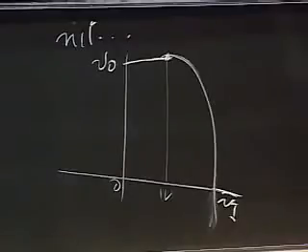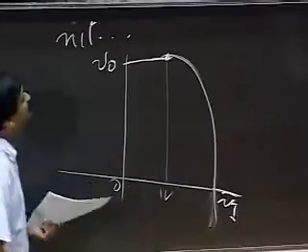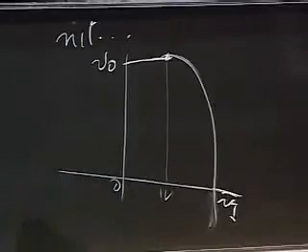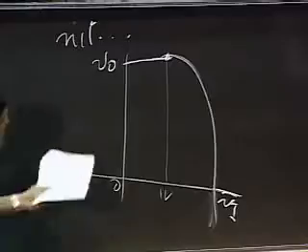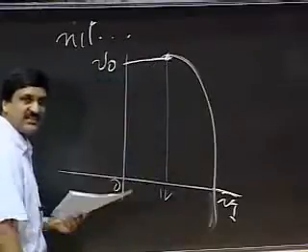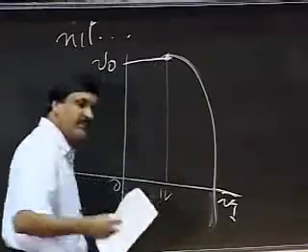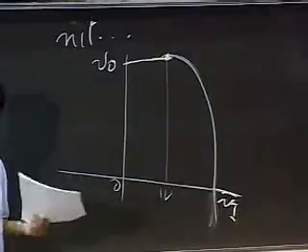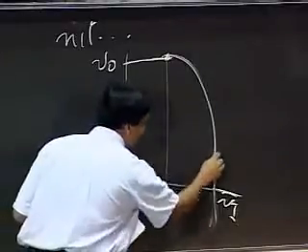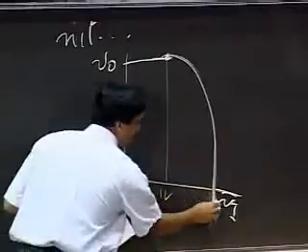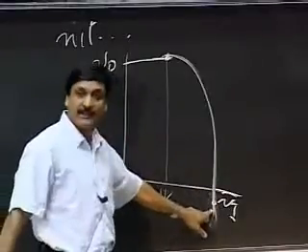But if I told you that this device that I have here, this dependent source, is a practical dependent source, a device that I have physically built, and I also say that it's a passive device, in other words, that it cannot produce power, it's like a little resistor, it doesn't produce power. If it's a passive device, then you're going to say something doesn't make sense here. Mathematically, it says it should look like this. But what's special about a point down here?